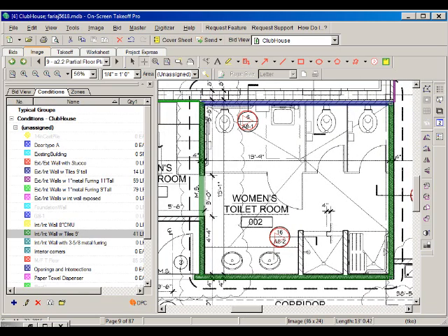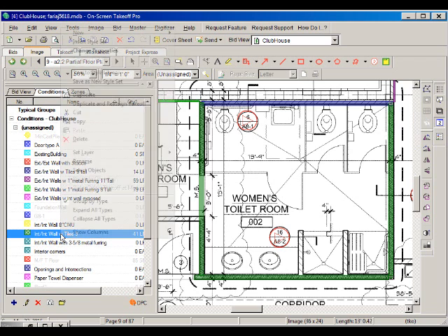This section here is the one where we saw that has double studs. So we will need a new condition for that, and this has tiles on both sides. So this will be this same one, but with tiles on both sides. Same 9 feet tall.